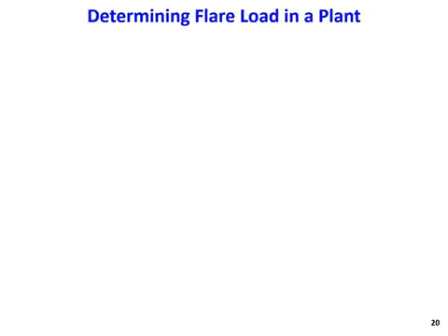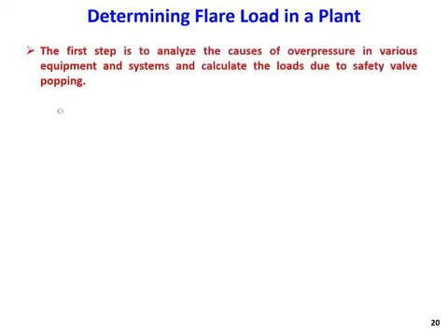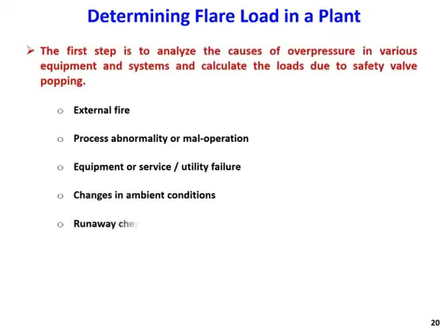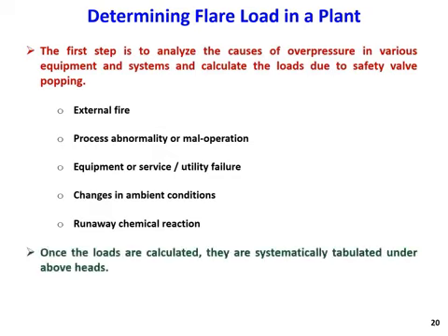Next, we have determining the load on the flare. So as I said, we design the flare based on the maximum capacity, or worst scenario, that all these safety valves come into action. That's the worst scenario.